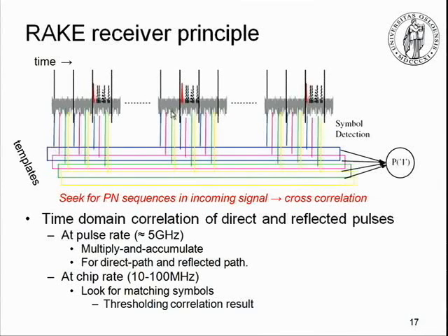Cross-correlation is a demanding computation. It's not used too much in time, we tend to go to frequency, just because it's so demanding. At each point in time, I have to multiply my template with my signal.